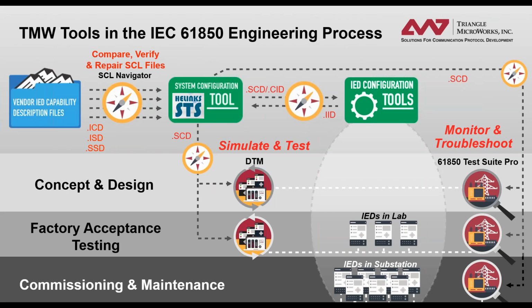Yeah. So if you update in Helinks a communication link, then Helinks proposes you to regenerate the communication configuration for every concerned IED, and indicates in a lifecycle support the set of IEDs you have to reload to make this consistently happen. So you do not have to reload all the IEDs, but just the IEDs that have changed.